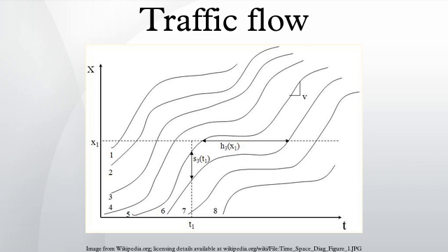Traffic breakdown at a highway bottleneck is a local phase transition from free flow to congested traffic whose downstream front is usually fixed at the bottleneck location. Such congested traffic is called synchronized flow. Within the downstream front of synchronized flow, vehicles accelerate from synchronized flow upstream of the bottleneck to free flow downstream of the bottleneck. At the same bottleneck, traffic breakdown can be either spontaneous or induced.